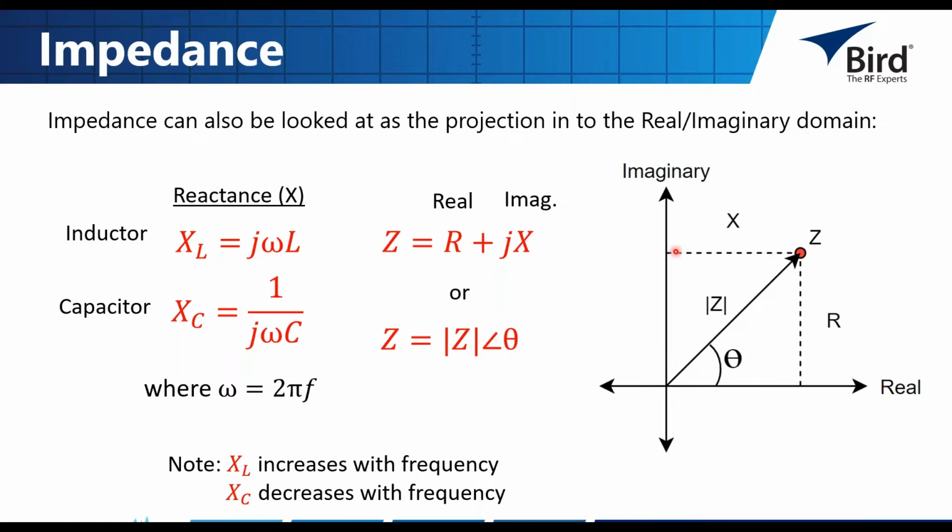And here to the right, you see a plot of the imaginary and real axes. This is how we're describing impedance, using the real portion and a reactive portion. So when we're talking about complex impedance and thinking inductors and capacitors, we're looking at reactance. Here we have the equation for reactance of an inductor, and here we have the equation for reactance of a capacitor.